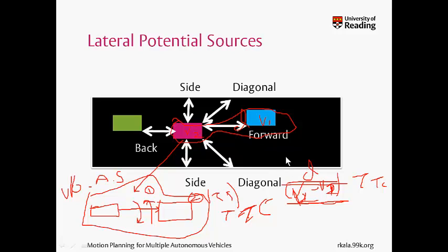And why did I take time to collision and not distance as a measure? It's because if this vehicle is traveling very slowly, but it's traveling in the forward direction, then I can nicely take a steering like this. But on the other hand, if it was a static obstacle, I'll have to turn immediately. If this is a fast moving vehicle, then I can be more comfortable, because I know by the time I reach here, it would have reached somewhere out here.